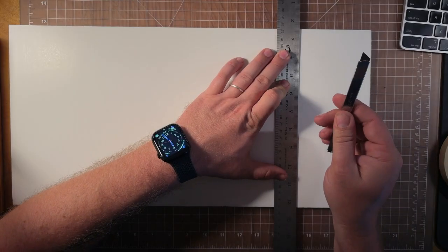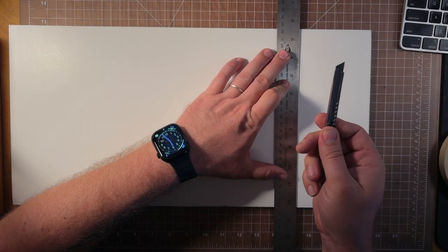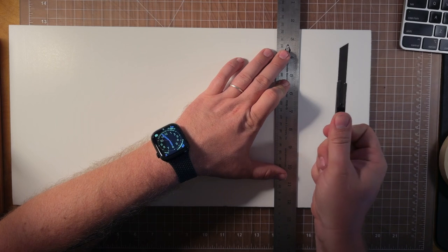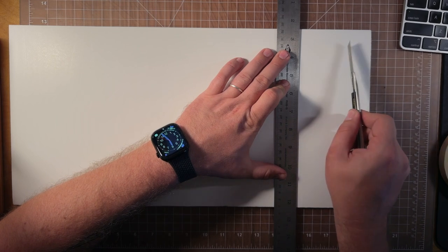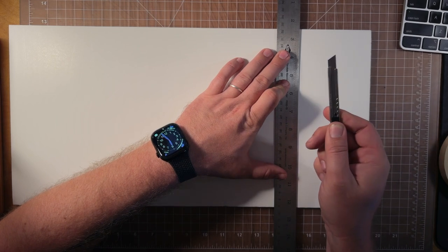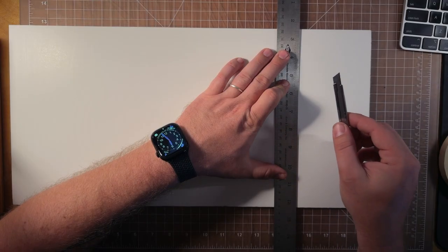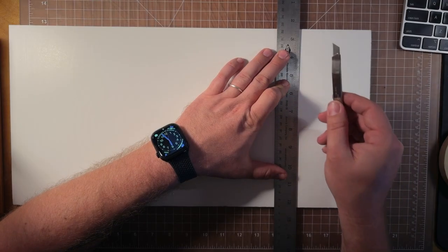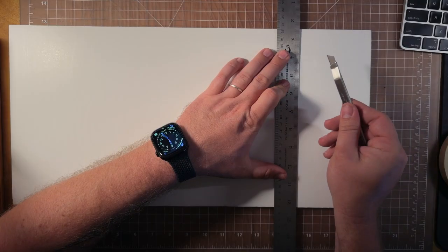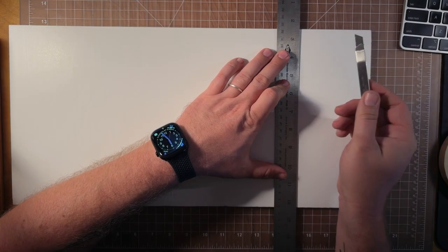And using the blade, with this Olfa blade, I have the retractable blade. Don't have it way out in space where it can wobble around on you. You want to have it only a couple clicks out so that the blade can't move. With regular X-Acto blades, that's not so much of an issue, but you don't want to have the blade all the way extended, is what I'm saying. It also increases the risk that you could cut yourself.